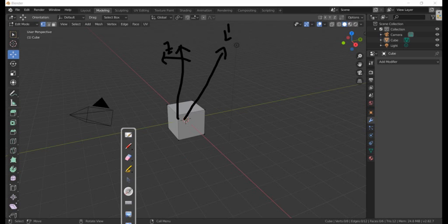You have three primary planes: xy plane, yz plane, or xz plane. You have to push this line so that it will lie on some primary plane. Now you can see that at this position it is not lying on any of the three primary planes.